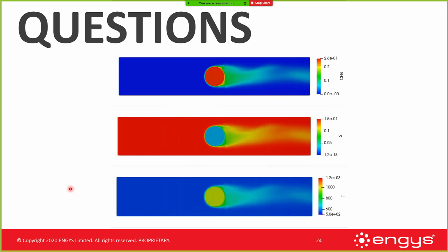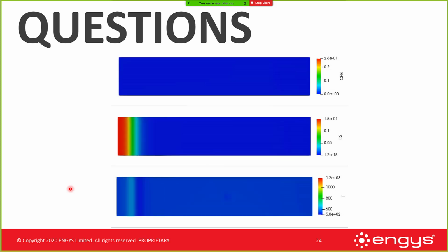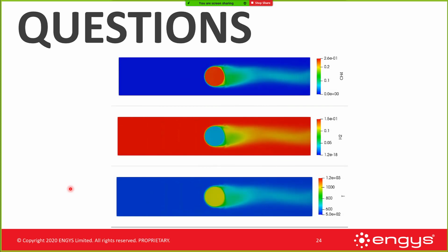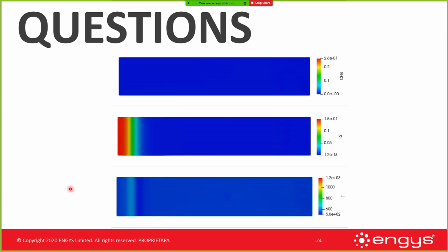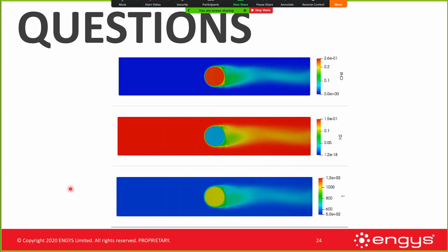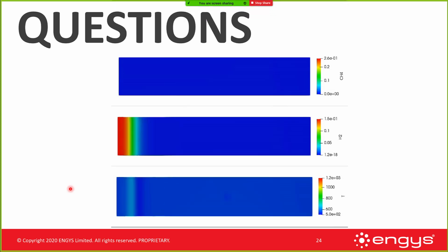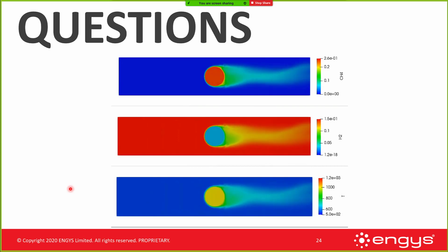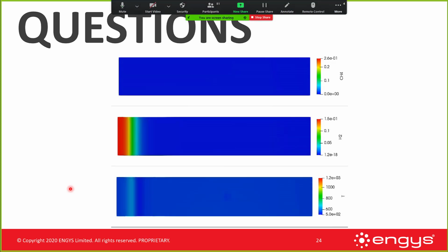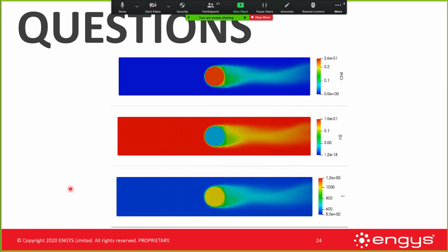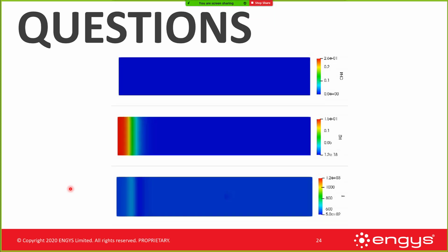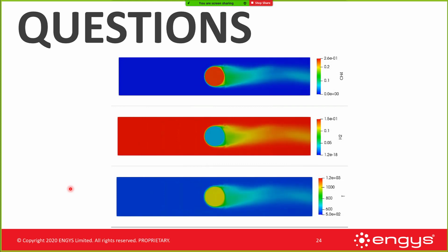All right. Yep. And then another question. It seems to me you are close to DES resolution with the mesh, but I believe you are running a RANS turbulence model. Wouldn't it be better to switch to DES since there is virtually no cost involved? Yeah, it totally would. And I would love to do that, but to be honest, the meshing resolution was really down to that level because I needed to be able to resolve a lot of these small features and small contacts within the particle structure itself. I'd be willing to try that.